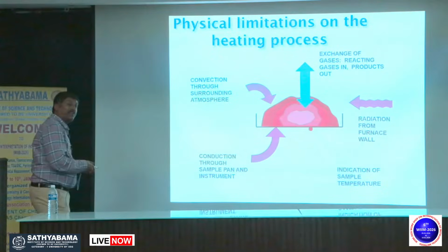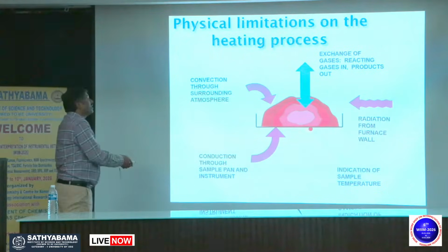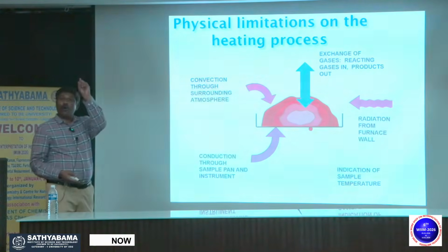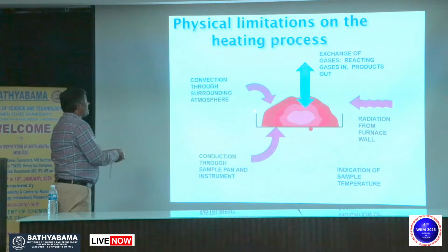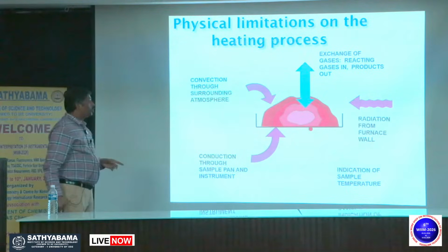The pan's heat capacity means it can retain heat for longer, so your actual measuring temperature will change. Chances of error 1, based on the heat capacity of the pan. 2, radiation.